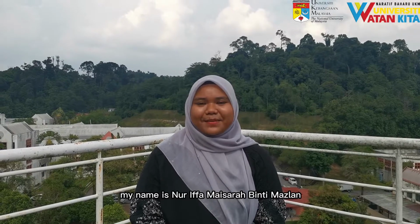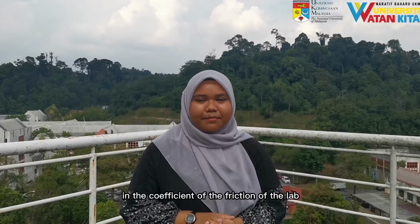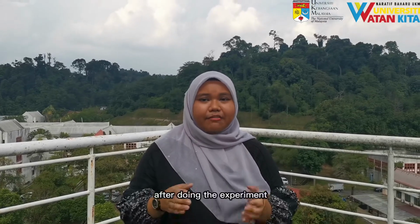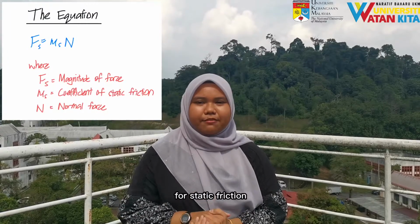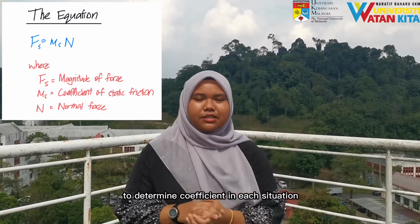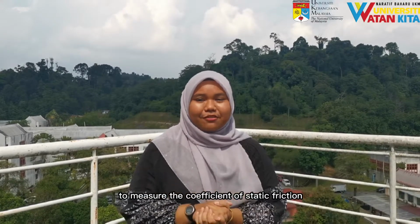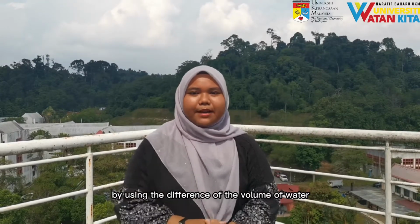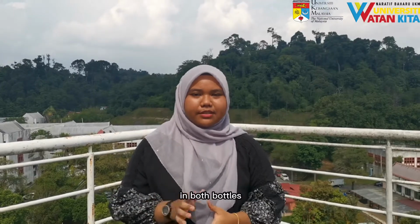My name is Iffa Binti Mazlan, and I will handle the introduction part of this lab. In the coefficient of static friction lab, we are required to measure static friction for a rope and the fixed drum. After doing the experiment, we were expected to apply the equation for static friction to determine the friction in each situation. This experiment is an easy way to measure the coefficient of static friction. The coefficient of static friction was identified by using the difference of the volume of water in both bottles.